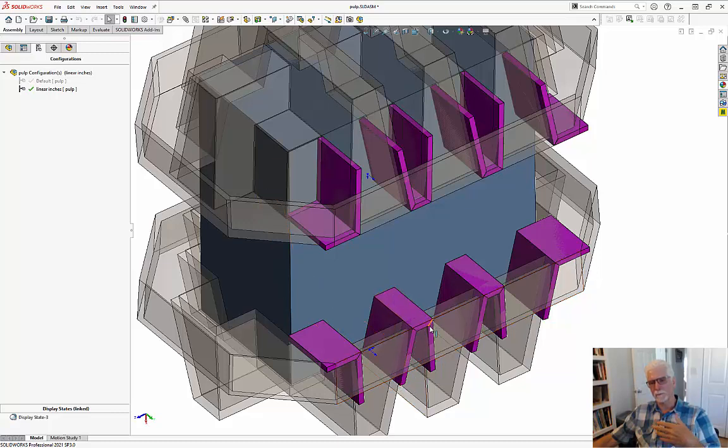So instead of figuring out square inches and stress, we're just going to use what these are, always 1/8 of an inch thick in my world, and so we've come up with a number called linear inches. And so what we do in SolidWorks, we're going to add up the linear inches of all these different walls, and so the linear inch times the thickness is going to give us the square inches that's going to be compressed due to the load, and that's what'll sort of relate to stress, right? And that's what's going to cause it to compress.